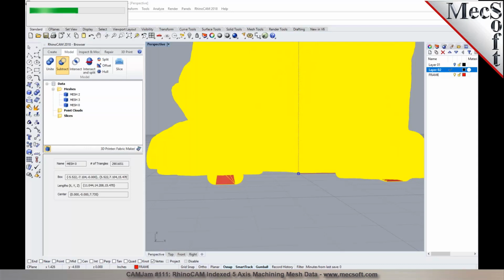Okay. Now I saw that you converted a NURB to a mesh. Can you convert a mesh to a NURB? You could. There are some tools available in Rhino that's called mesh to NURBs, and also you can do a drape. But the process of going from NURBs to mesh is a lot easier versus mesh to NURBs. It's a little bit more involved. So Rhino has some tools that can let you do it, but there are also some additional third-party plugins in Rhino which probably offer more control over it.